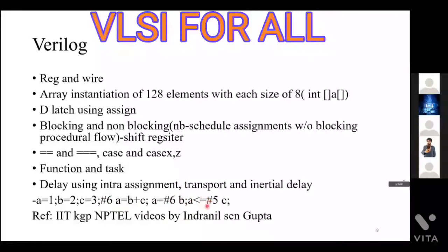For non-blocking, as I have said, the flow will be continuous. There is no need to stop. There is no need to wait for this delay for the next statement to be executed. But for blocking, the delay will be significant for the next instruction. For non-blocking, this is not significant. You can see some reference videos related to this.